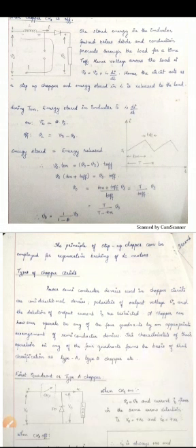From this equation we can infer that the output voltage V0 is always greater than the input voltage Vs. This step up chopper is usually employed for regenerative braking of DC motors.